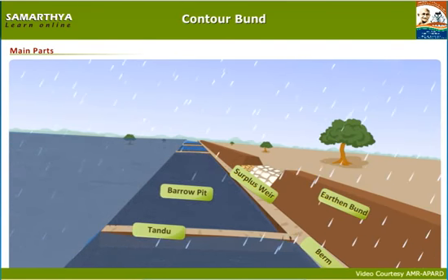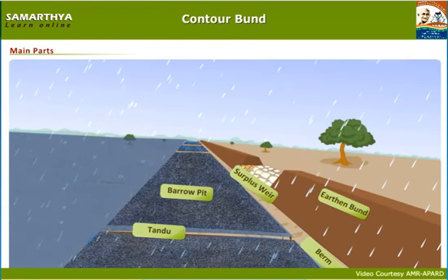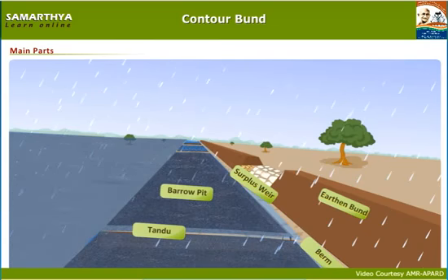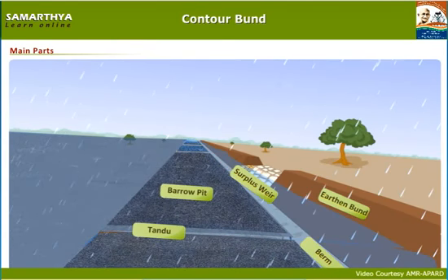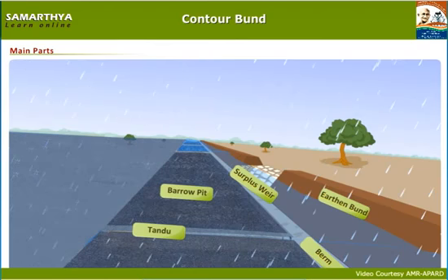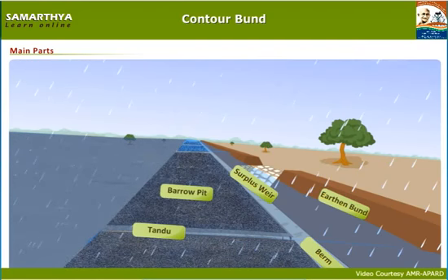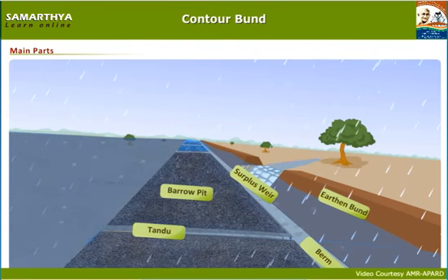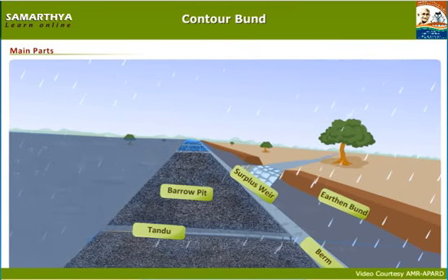Rainwater thus flows towards the lowest slope, and separation mounds prevent accumulation of water at one place and work as a barrier to the water pressure so that the earthen bund will not breach. Excess water comes to the earthen bund, then the surplus weir discharges water. The surplus weir is constructed across the natural stream of the field.